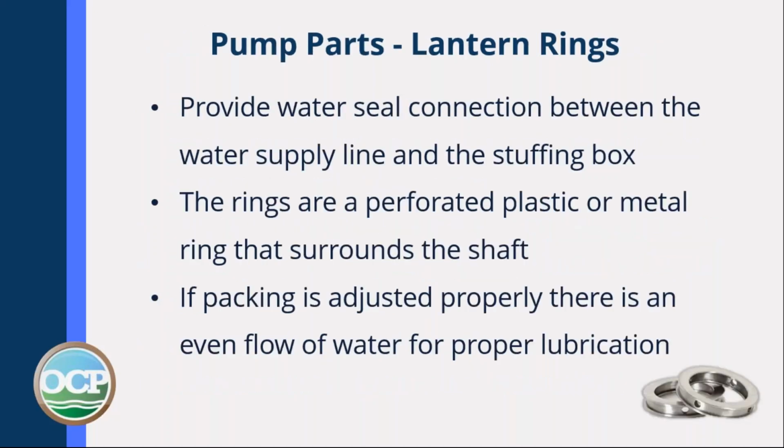There's the lantern rings we were talking about. Lantern rings provide a water seal connection between the water supply line and the stuffing box. The rings are a perforated plastic or metal ring that surrounds the shaft. If the packing is adjusted properly, there is an even flow of water for proper lubrication.